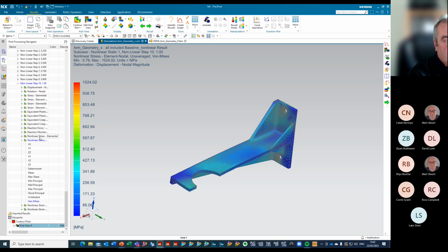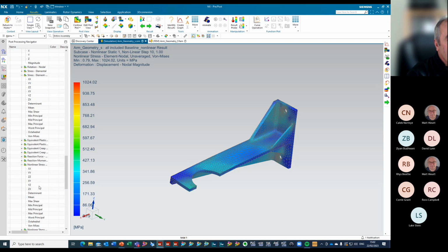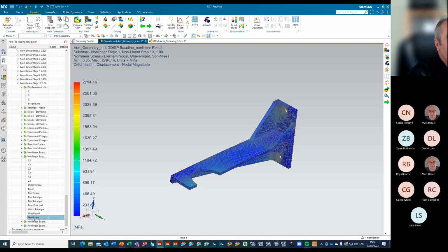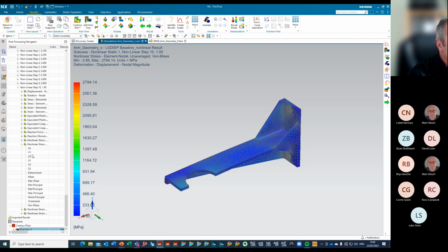We don't get the nonlinear stress as an output. We only get that when we've got our material nonlinear curve and it's starting to work on that. So that's where you would start and see the values. But you wouldn't see it if you didn't have the material nonlinear. You see it because of LGDISP, but if you go into here, it just lists what the stresses are.